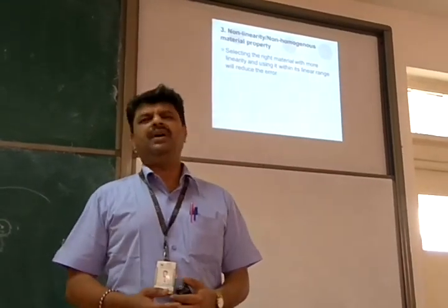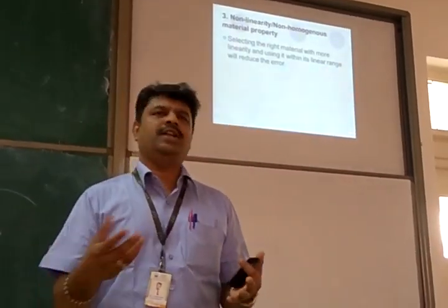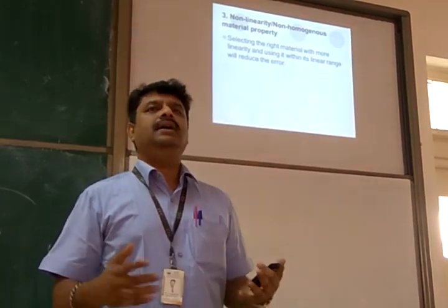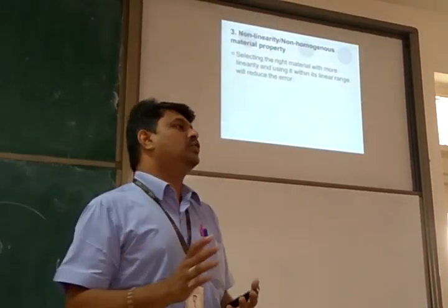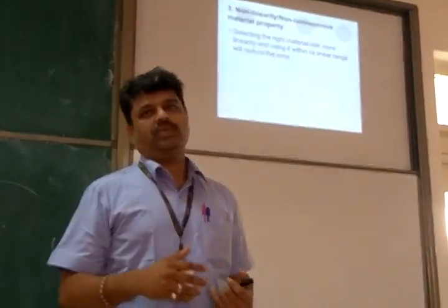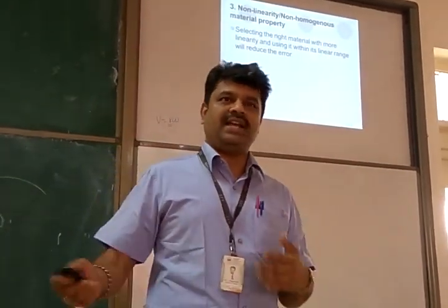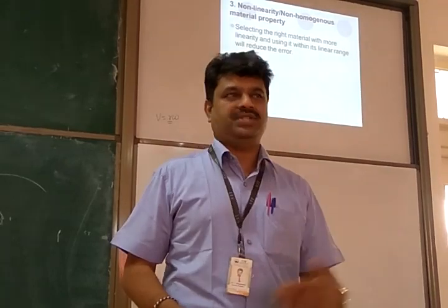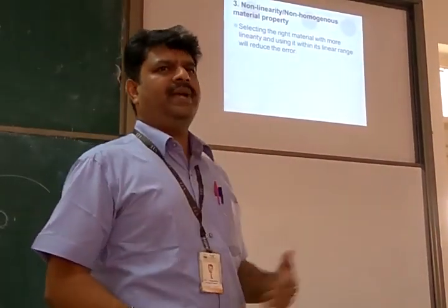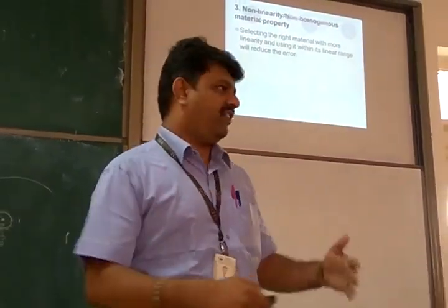The difference would be very minor according to the carbon content, but still the non-homogeneity is mostly because of the manufacturing process. So you have to put a tight, stringent rule on the quality and check the manufacturing process. Nothing big can really be done as a counter effect of those effects.